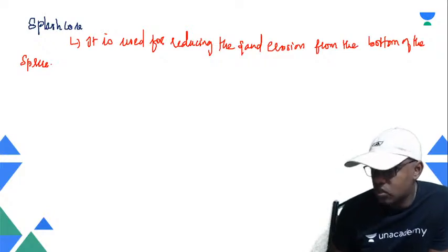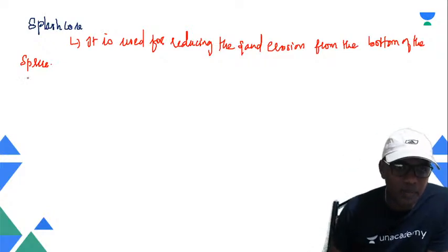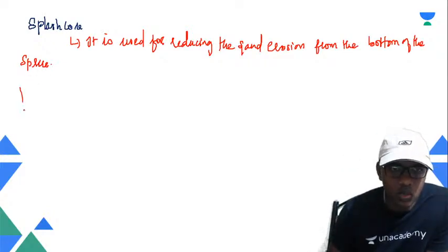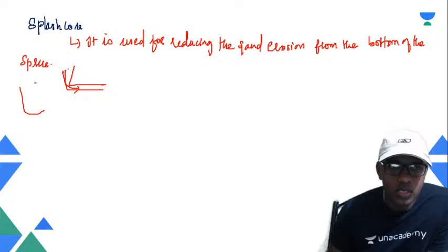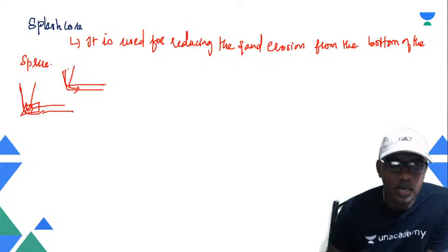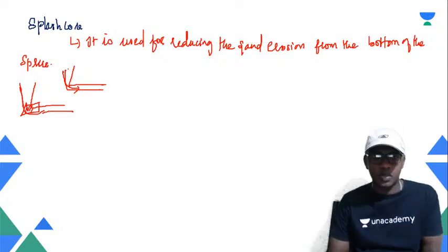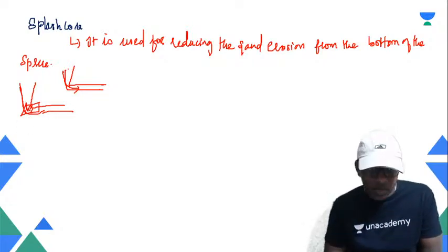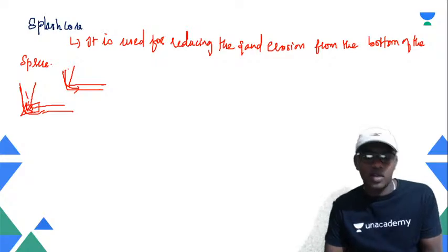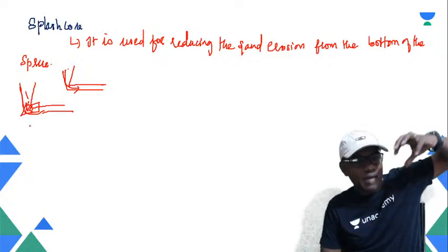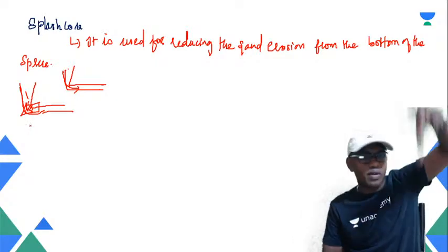It is also made of ceramic materials, it can be, and with a high porosity. So what happens, when the molten metal falls in this vertical chamber and passes with a sudden change, there is a gradual reduction in its speed, it goes like this, correct? So here you have the splash core. The splashes that cause the erosion can be reduced. At the same time, it can filter a lot. This will reduce the impact because it is traveling with such high kinetic energy, falling from a height.